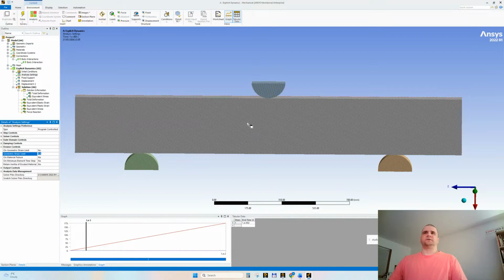This will allow large displacement, large deformation, yes, but it's suitable for ductile materials, and we need the maximum strain limit to be something like, from my experience, around 0.42. You will see in a few minutes what I'm talking about. So this will ensure a nicer, proper fracture of the concrete.